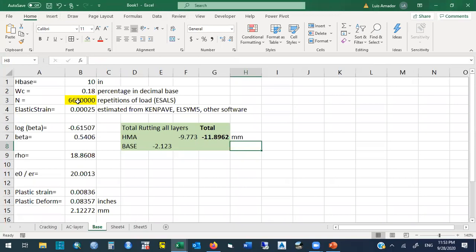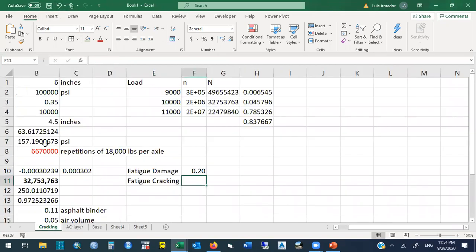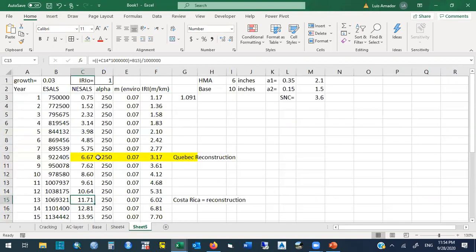So that means they already went beyond the maximum rutting. They are tolerating beyond what AASHTO is suggesting you should tolerate. And of course, if we go to cracking, I say how many? 11.7, right? Yes, exactly. So you are at 36% damage. So they are tolerating further damage. So it's not that easy just by this number to know.